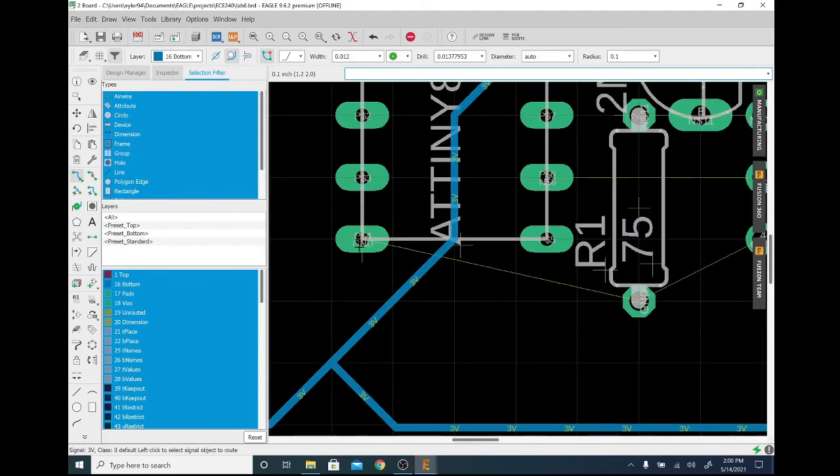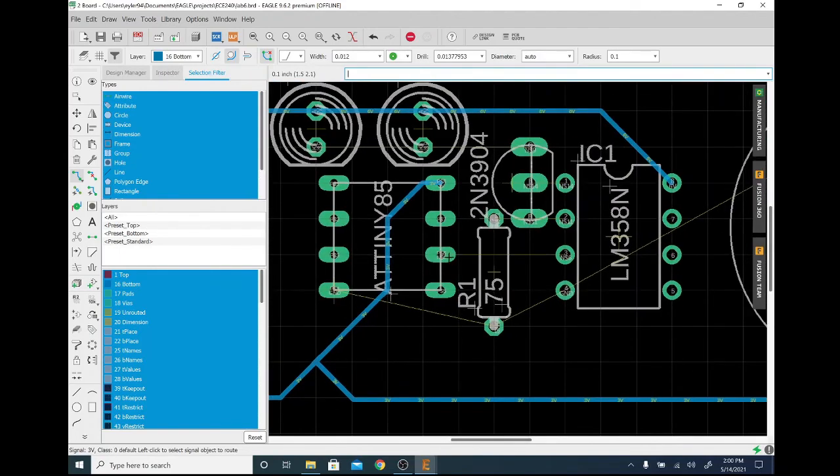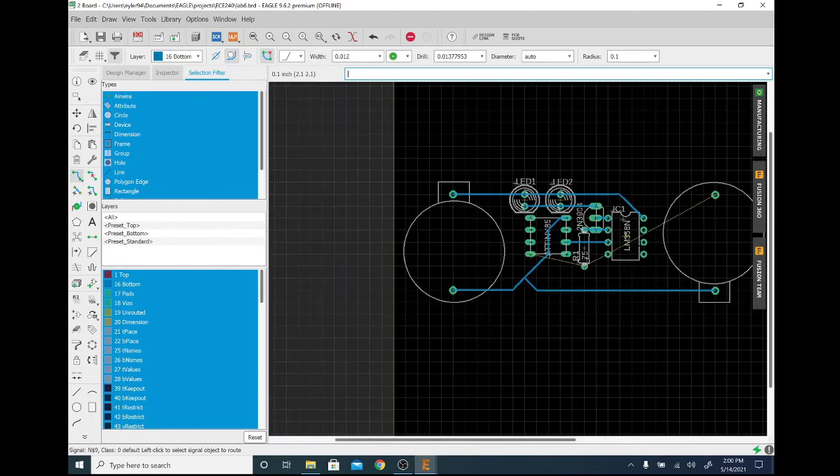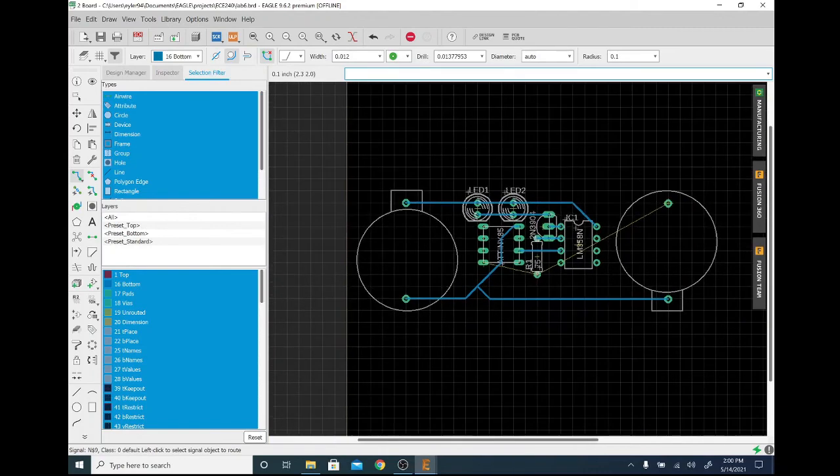And if you notice, I'm ignoring the ground for now. The reason why I'm doing that is I am going to use what's called a ground plane. Ground planes are very important for both dissipating heat, as well as decreasing the noise in your traces. A wire in any direction will act as an antenna. And if you have it next to the ground wire or ground plane, that acts in a capacitive role to decrease the noise on that signal. It's not perfect, but it really helps.